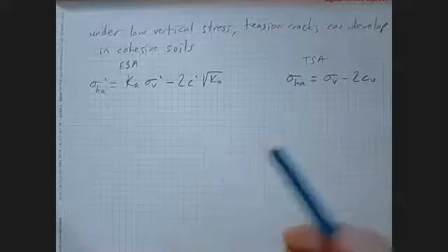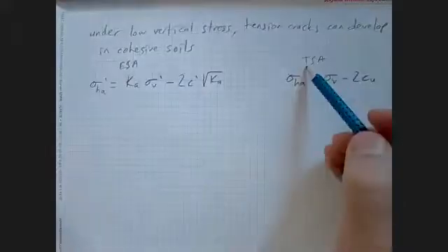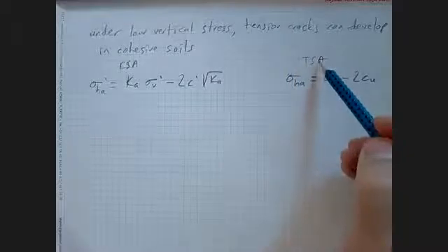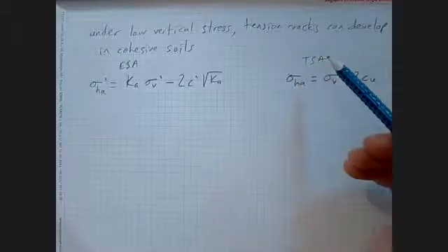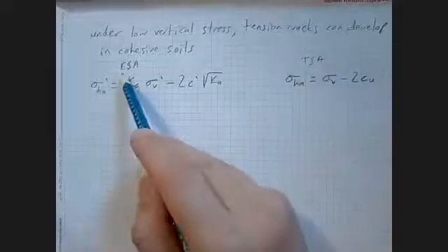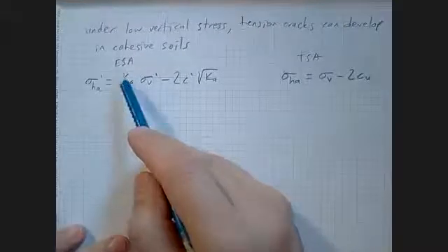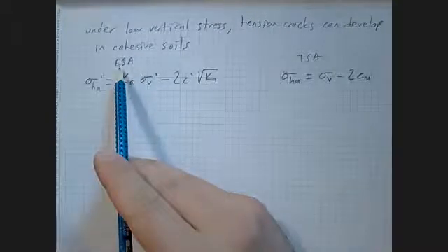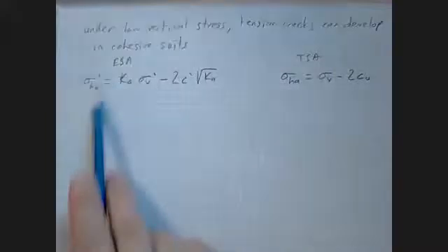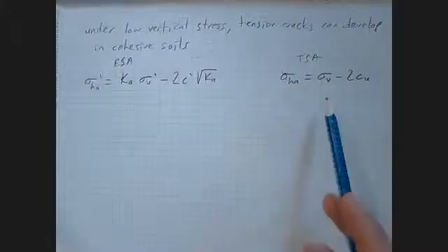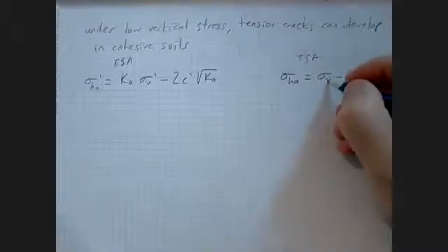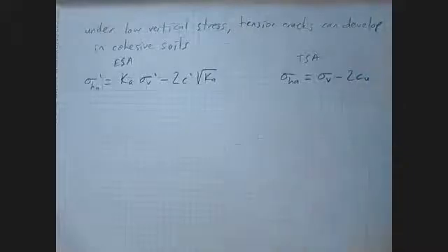And how do we decide on that? You decide whether to use total stress analysis based on whether it is undrained mode. So it is like a short-term change in stresses versus a long-term change in stresses. If a slow change in stresses is happening, or if you are wondering what happens in the long term to your problem, you need to use the drained analysis. If you are looking at short-term changes, you need to use the undrained analysis.